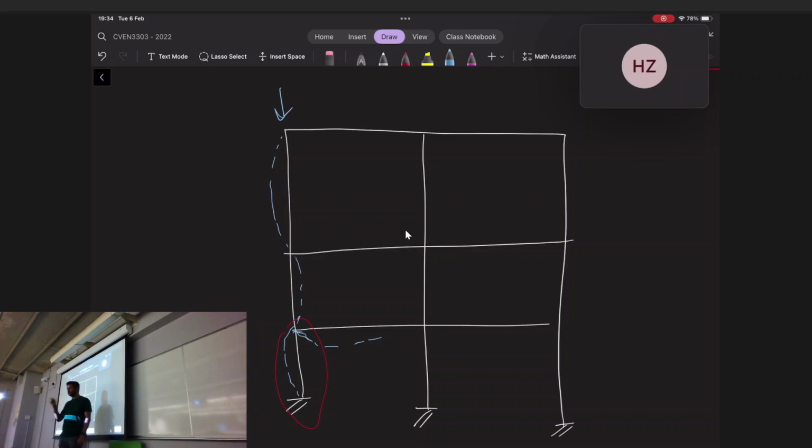You see that the terms I brought up just now, I talked about stiffness, right? So how this column will deform is based on the stiffness of the column above and the stiffness of the beams that are framing it, basically the stiffness of the members around it. So this column runs between the bottom node and the top node.